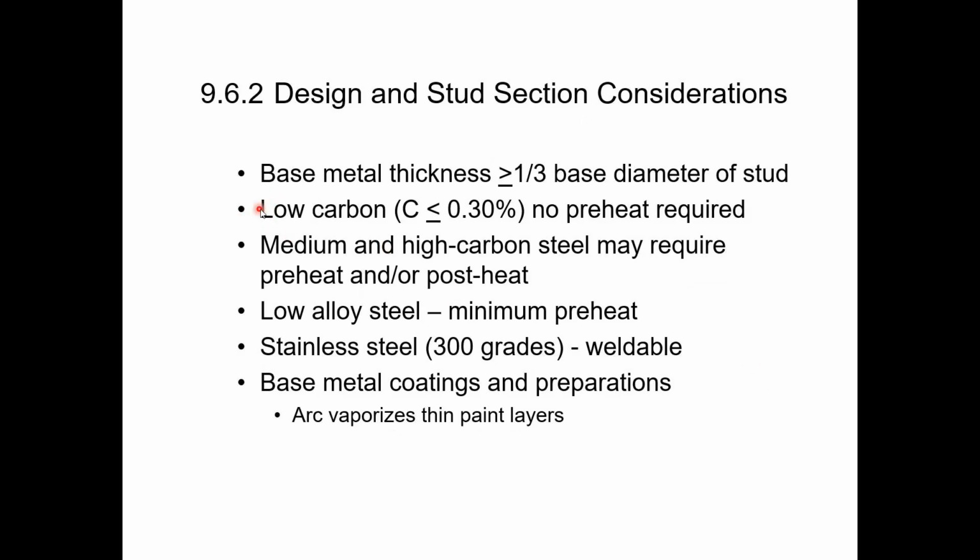Just so you'll know, you might be thinking, well, do I not have to check carbon equivalent for this? The answer is you don't need to check it because these studs are provided to you. The material that's used to make these studs usually has a carbon equivalent of less than 0.3, or carbon content less than 0.3%. So no preheat is required.